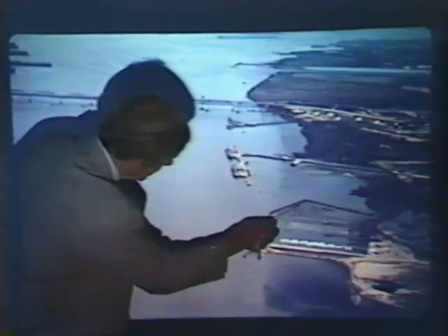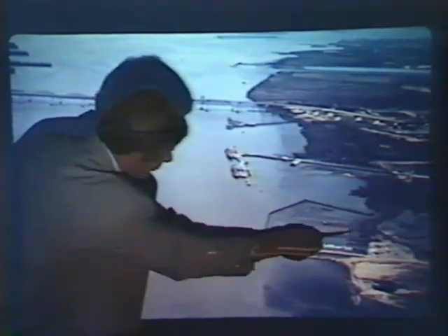The entrance was out in the deep water, which is the best location, but it's still affected by flows that flow around this and by it, so that during a rising tide, water flows around here and into this entrance and then back out. So the sedimentation pattern is a strong sedimentation near the entrance and not very much near the back. That's typical of a situation like that. It would have been better to have had the opening somewhere in the middle, so there was a little bit of dispersion each way, but probably not that much better. Certainly wasn't worth tearing down the breakwater and building a new one, building a new entrance. That's about the best you can do with that harbor.